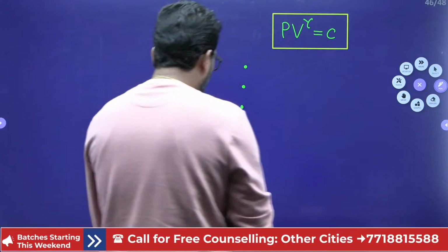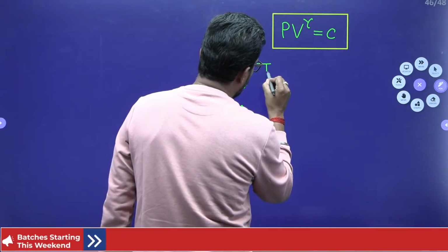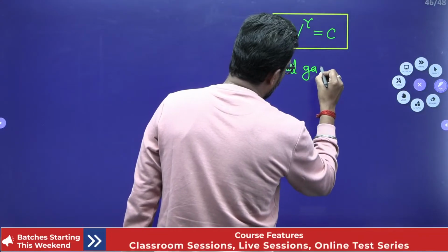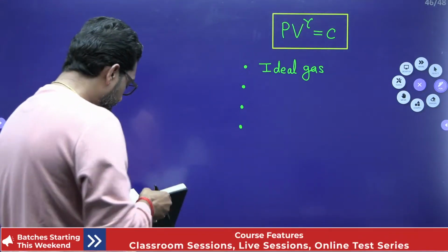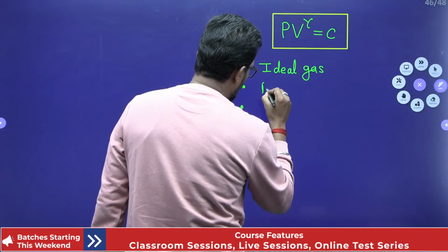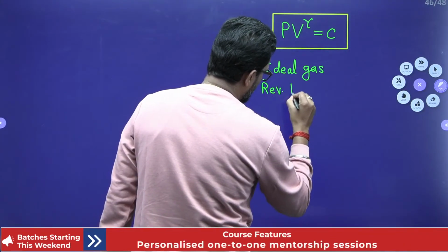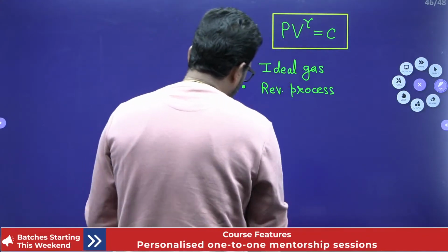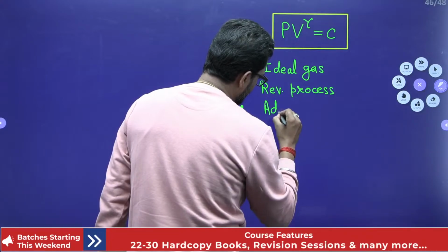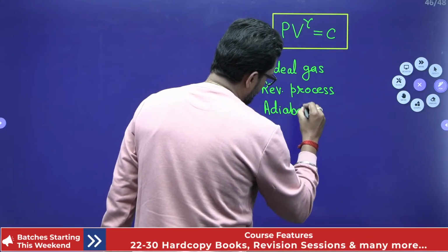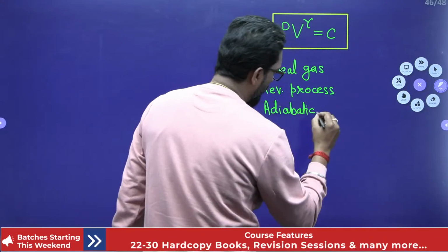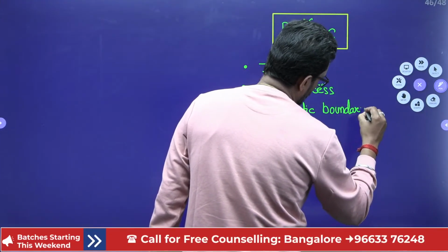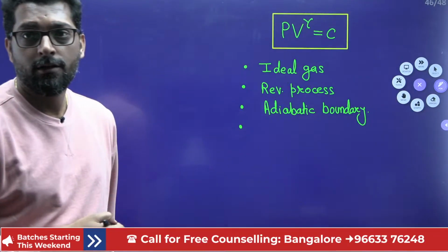This equation is valid for first, ideal gas; second, reversible process; third, adiabatic boundary, that means in which there is no heat transfer.